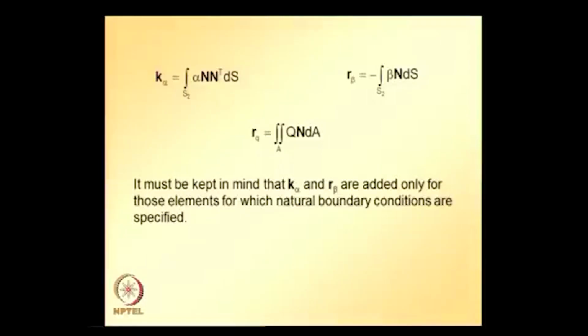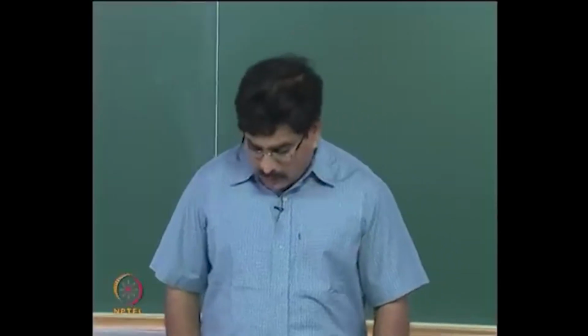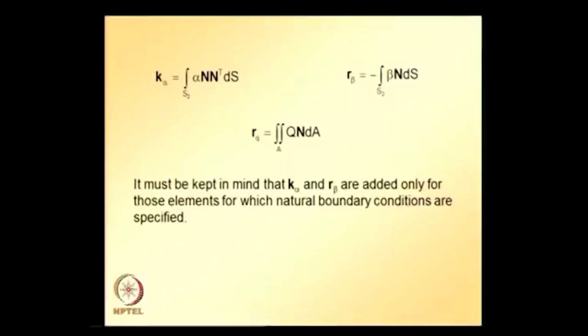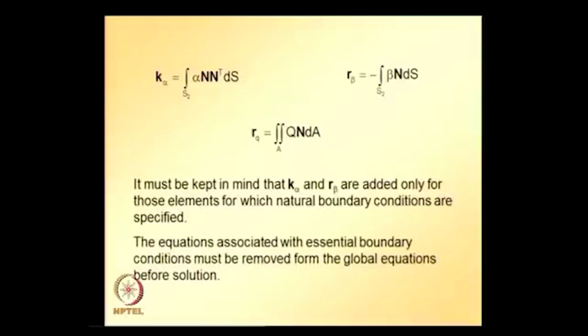So, given the governing differential equation and corresponding boundary conditions for a particular application, the first job is to identify what these kx, ky, p, q coefficients are. Then we can easily assemble the finite element equations corresponding to that particular element if you know the shape functions and derivatives of shape functions. The equations associated with essential boundary conditions must be removed from the global equations before solution.